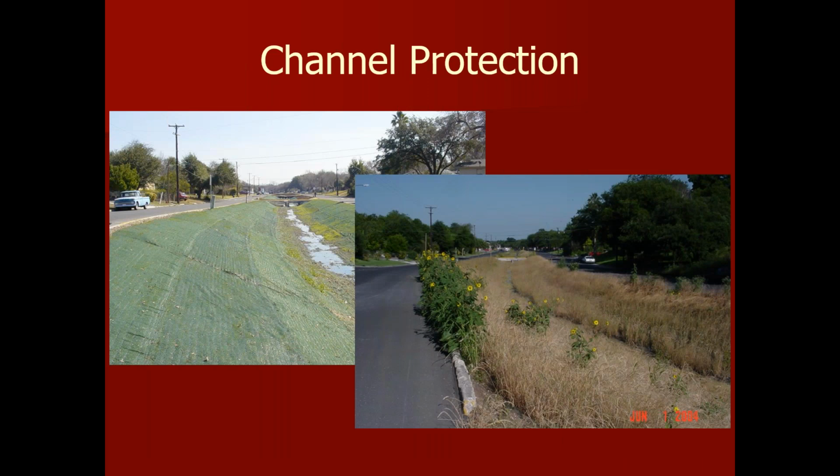You see a lot of urbanized areas. As we get more and more people, we have to control that stormwater and be able to safely and effectively convey it to its downstream source. And with different types of vegetation, you can see we have an area here where the channel was constructed and formed, low flow channel in the bottom, and then native vegetation allowed to establish and provide the supplemental protection over the TRM for these type of channelized